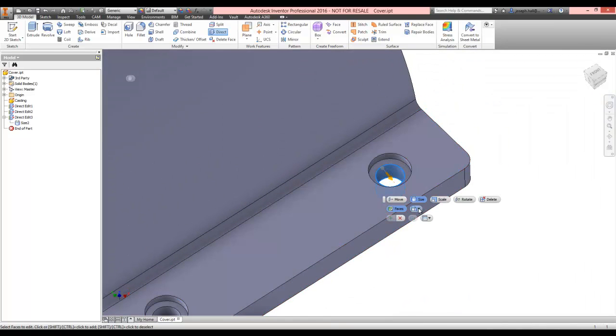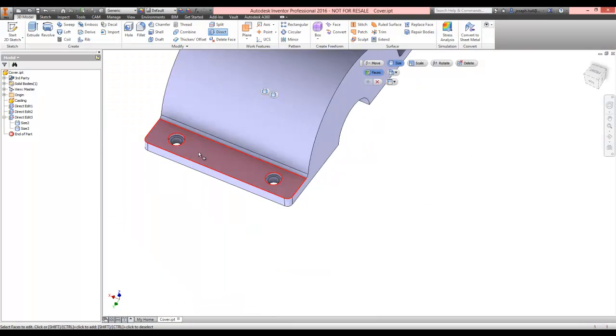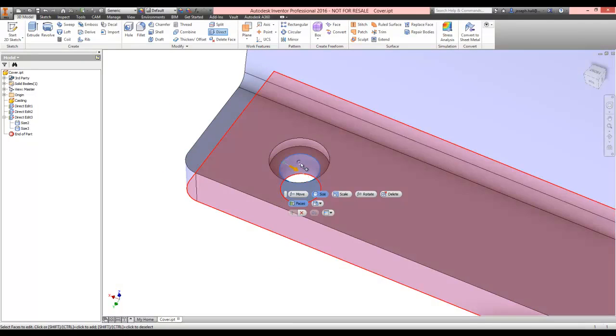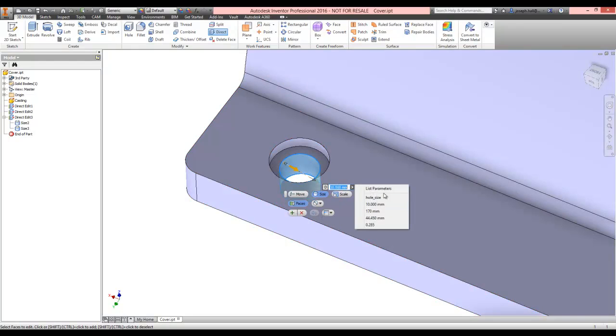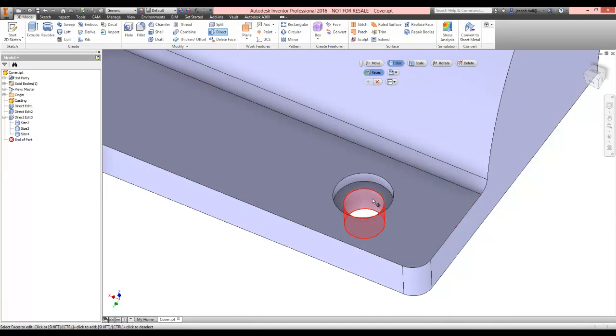Now I don't need to specify with these. I could just say equals hole size. Because it should know what hole size is, I'll actually press equals hole size. Because it knows what hole size is, it knows that that's now 10 millimeters. So I'm linking them together. There isn't an option, unfortunately, just yet to say show me parameters within this box. Oh, there is. Sorry, list of parameters, hole size. I was thinking of a different command then. Add that in. You can do the same thing here.